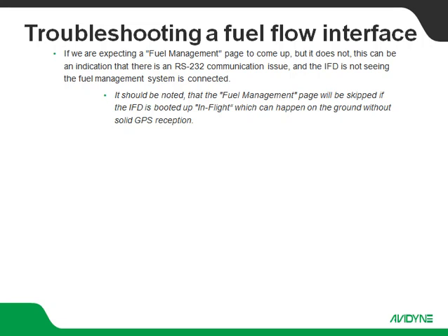That fuel management page, if it does not come up after the startup sequence and the allow ignore option for your Wi-Fi and Bluetooth, may or may not be an indication of a problem. If there's no fuel flow system communicating with the IFD, it's not going to take you to that page.